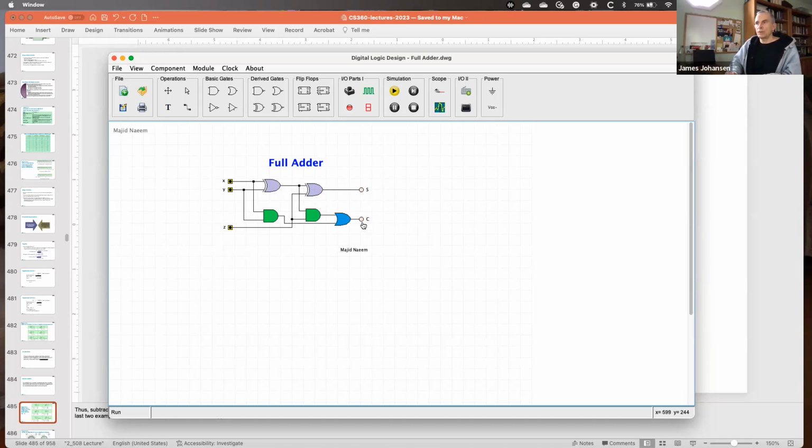This is where you need to have this carry-over bit. The difference between a half adder and a full adder is that a full adder deals with this overflow in the input as well, so this can be aggregated together. Basically we have three inputs. So let's go through that logic.